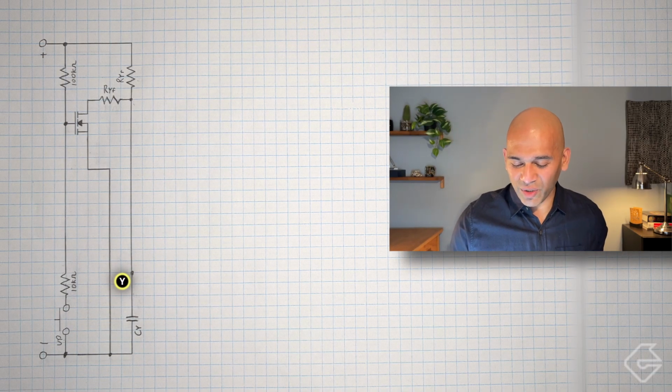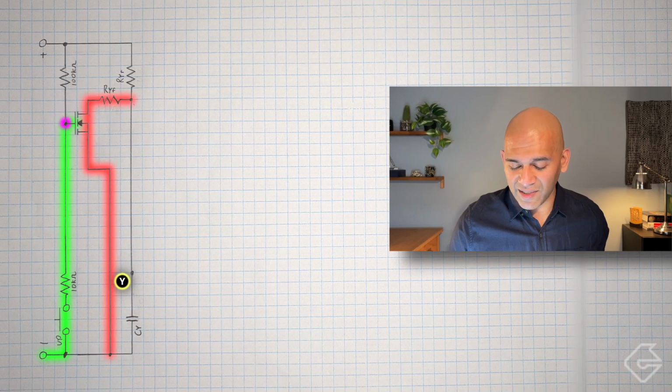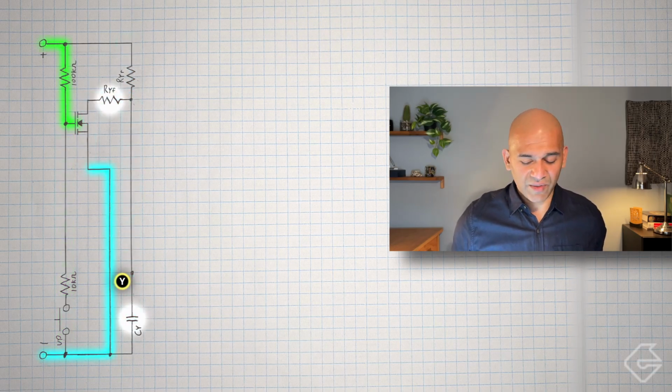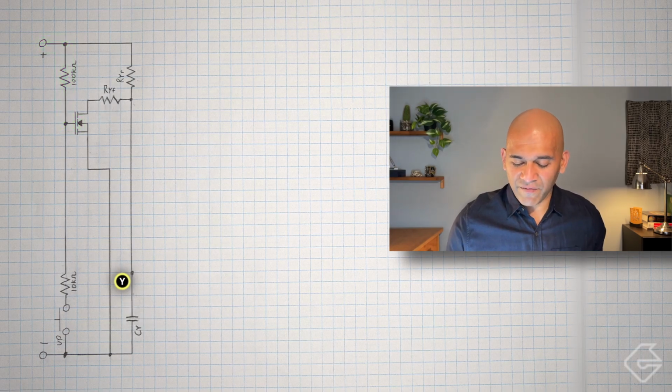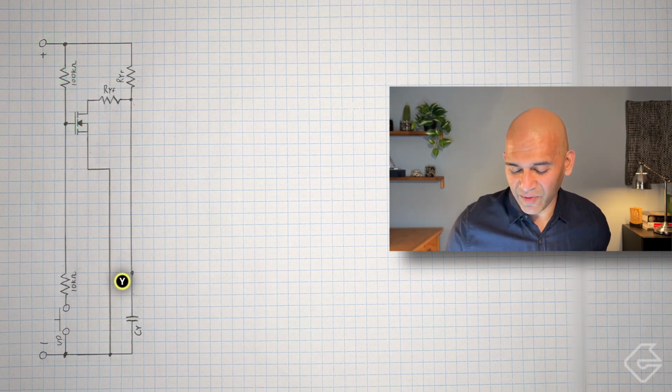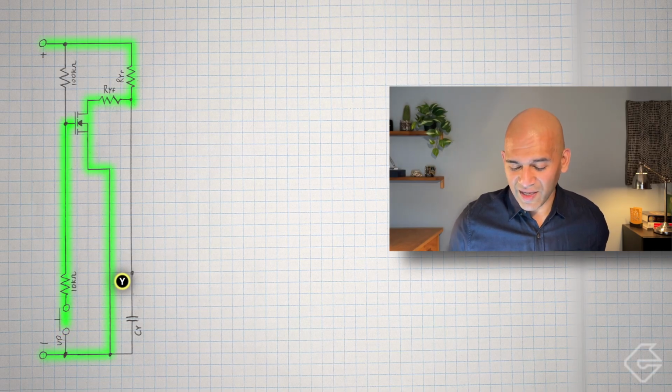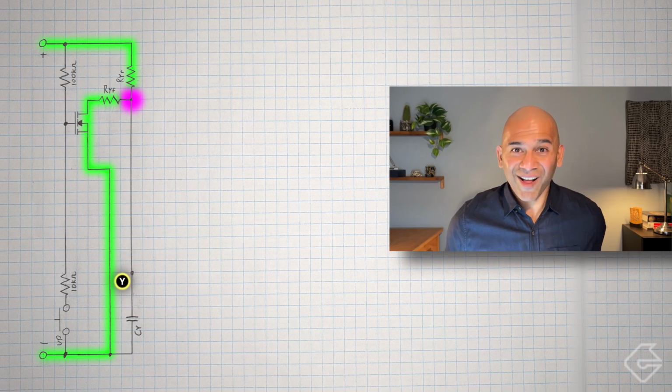Okay, so I can put two resistors in place here. Imagine what happens when I close that switch. Then this point over here goes to 0, which disengages the MOSFET, and it allows the charging resistor to take action. When I release the switch, the discharging resistor goes into action. So far so good. But if these two resistors are the same value, then when the switch is pressed, this point over here can never exceed half of the supply voltage. So if our supply voltage is 12, this will never go above 6, which means, again, I'll never get the 1 that I need over here. This is going to cause a problem.